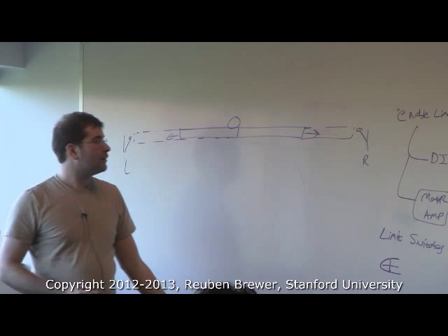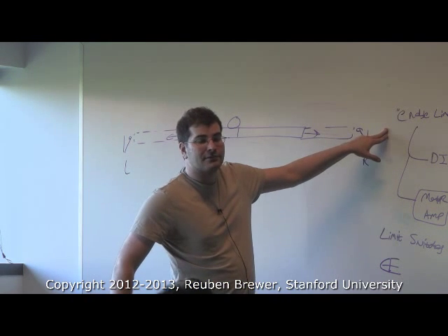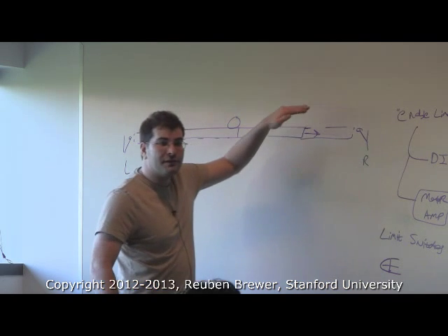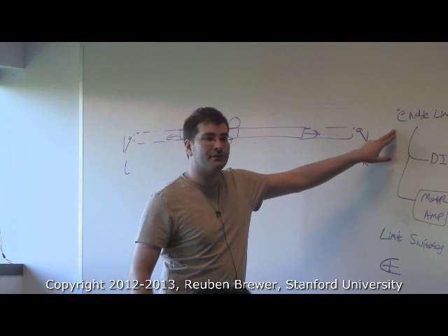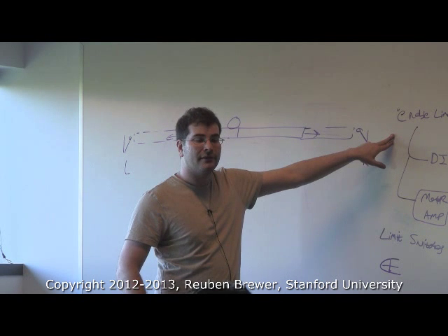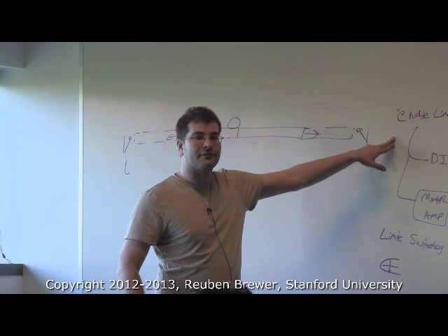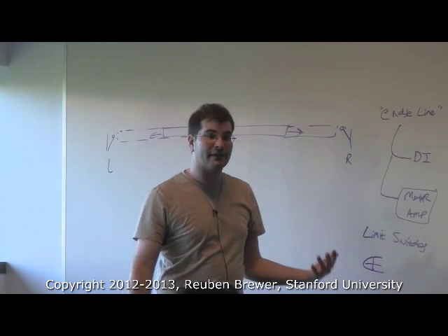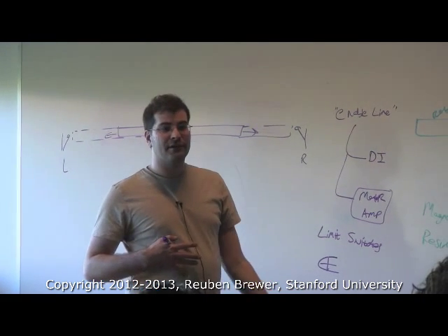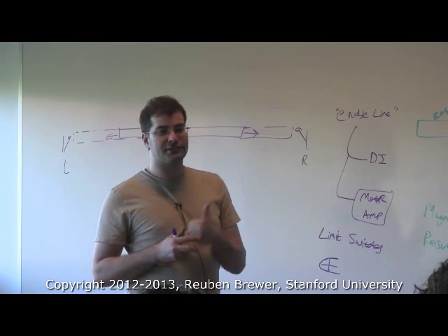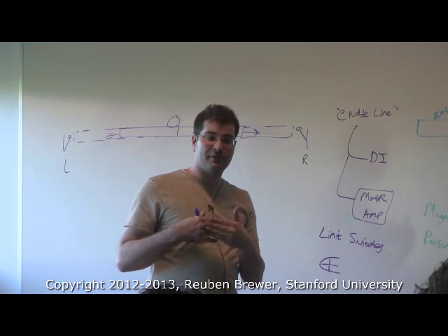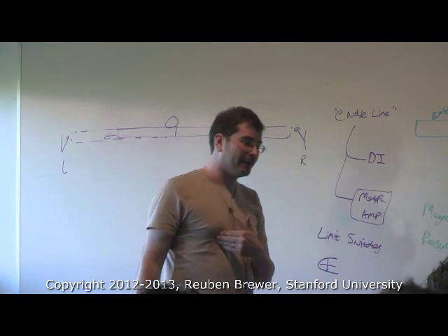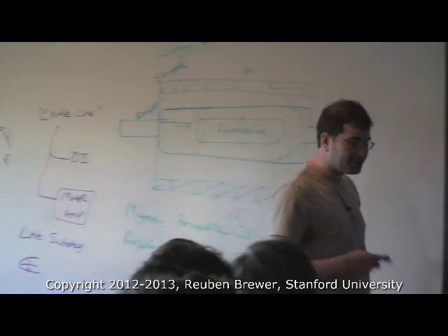Maxon motor amps only have an enable line. So the only thing you can do is feed the enable line plus left and right limit switches in an OR configuration into the enable line on the Maxon driver. But then it kind of kills your robot, right? Because if anything happens, you're done. I can't move out of the situation, so then you have to reset the robot. So I keep harping on the Copley amps, not only because they're industrial grade and they don't fail. They have really nice enable line plus left and right limit switches. Plus they give you actual torque commands and current. And if you get the digital ones, you set the transconductance digitally. It's really fast and easy.